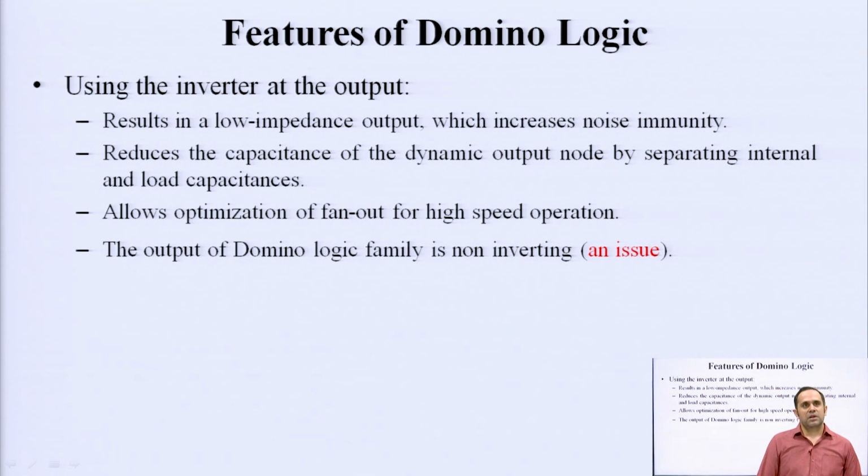Okay. Since you are connecting an inverter at the output for domino logic, you are basically inverting the output at every stage, and since the design by default was inverting, after connecting this inverter you are basically producing a non-inverting circuit.